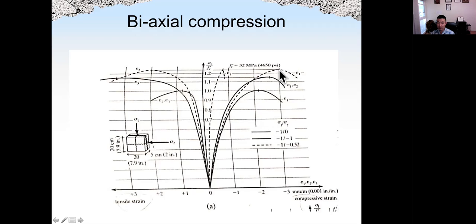Okay, you can see from here, epsilon 1 will increase, and also the peak strain, which is the strain level at the peak stress, also increases. The interesting part is the highest strength occurs at the sigma 2 level around 50%, okay, not at the highest sigma 2 level. Okay, so the higher compression actually is beneficial, but it's not the highest sigma 2 that will generate the highest peak stress.